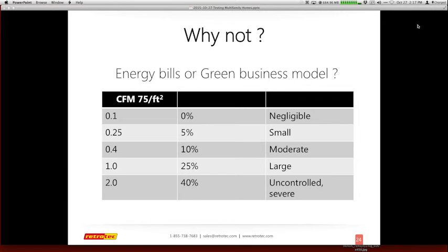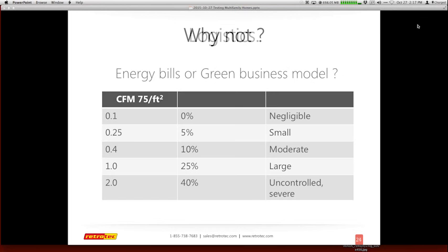One of the things that happens when you start getting to larger structures is they deal with CFM per square foot of the surface area, versus doing air changes per hour. When you start dealing with multifamily, it can mix into both of them, depending on if you're talking about individual units or your method of testing, which may actually be CFM per surface area.